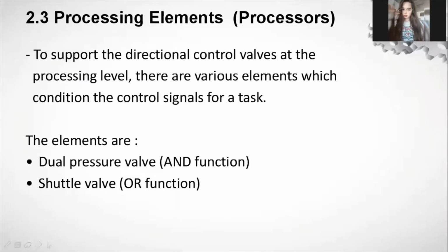Processing elements or processors. To support the directional control valves at the processing level, there are various elements which condition the control signals for a task. The elements are, first, the dual pressure valve or AND function. Second is the shuttle valve or OR function.